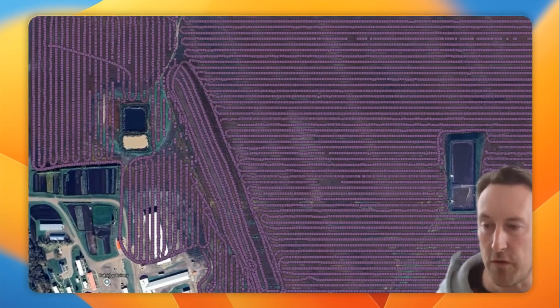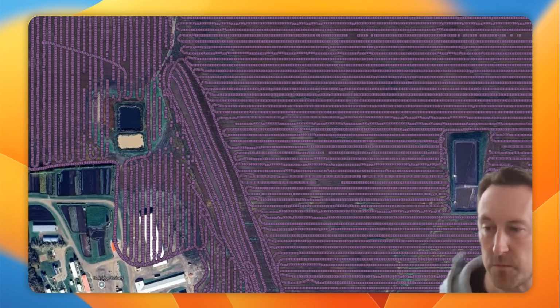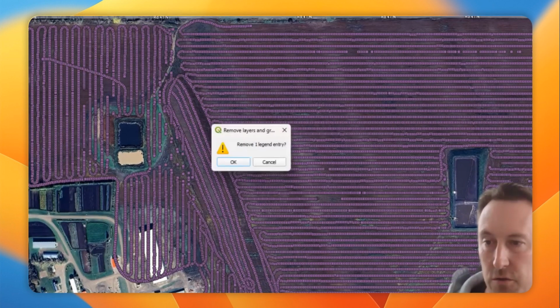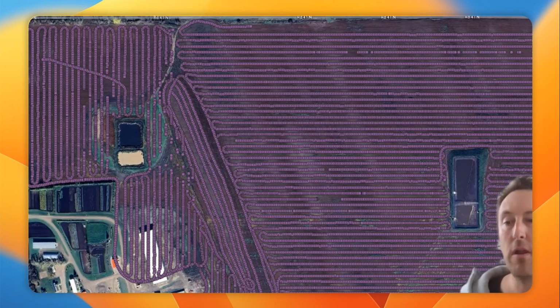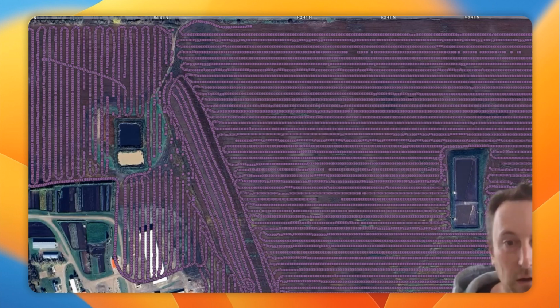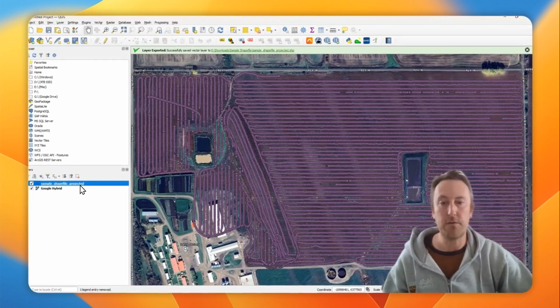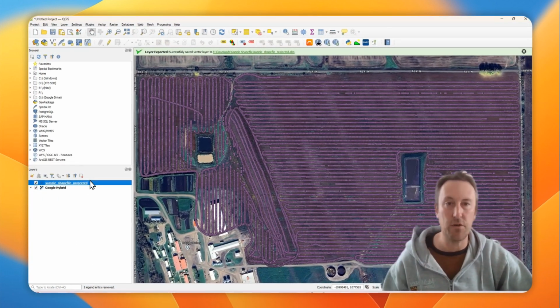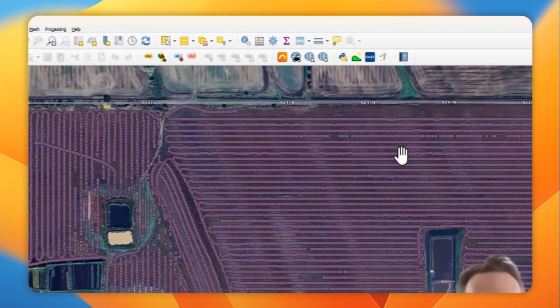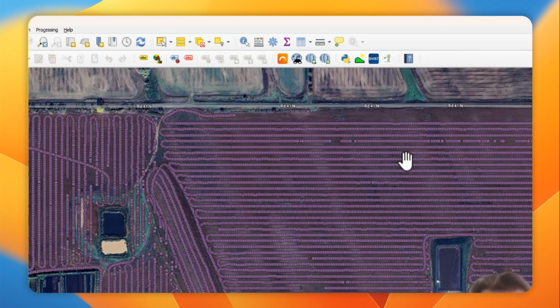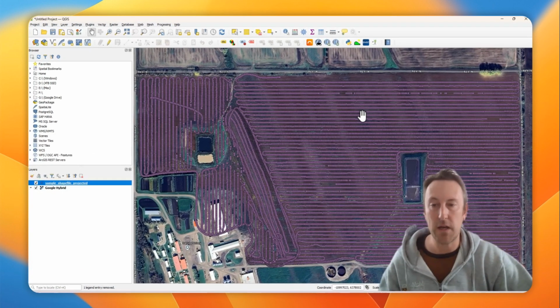So I'm actually going to remove the other one because it might just confuse me. Right click on that one and just choose remove layer. So now we only have our projected shapefile loaded, and it still looks good behind me. So now we're ready to run interpolation. So this is where we're going to create our smoothed grid and turn it into a GeoTIFF.